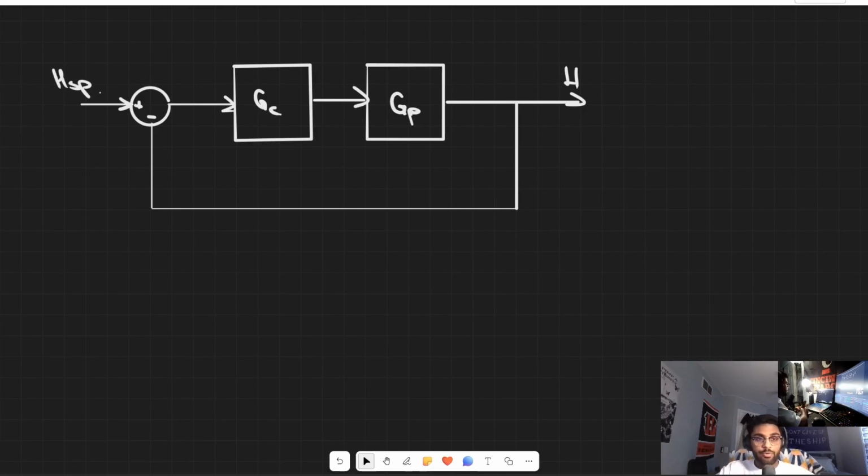So we are going to be continuing our conversation using process controllers, and this time we're going to be tackling something called an integral controller. So this GC here is going to be related to an integral controller this time, not a proportional only controller. First we can define the G for our process, and for this problem setup, we're going to say this is a third order process. So that is our process gain over tau s plus 1 cubed.